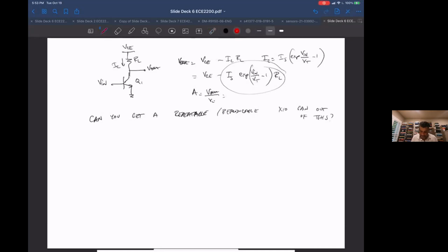Now this I sub S is a big factor in this I sub C, and that will vary a lot. If you guys remember, in production you will not get the same I sub S if you buy transistor after transistor.